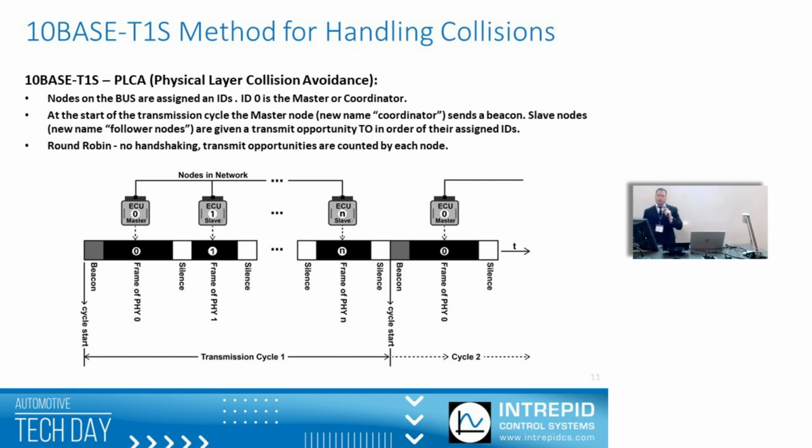And that is, 10BASE-T1S PHYs will have the ability in the future to discover for themselves how the network's configured, and you don't need to do that in software. No matter what, once everything's configured, it'll work the same. There'll still be a node 0, there'll still be a coordinator node, but what topology discovery does is on boot, it says, okay, how many nodes are out there? Who's going to be node 0? Who's going to be node 1? Blah, blah, blah. There's a whole negotiation that happens on boot up.